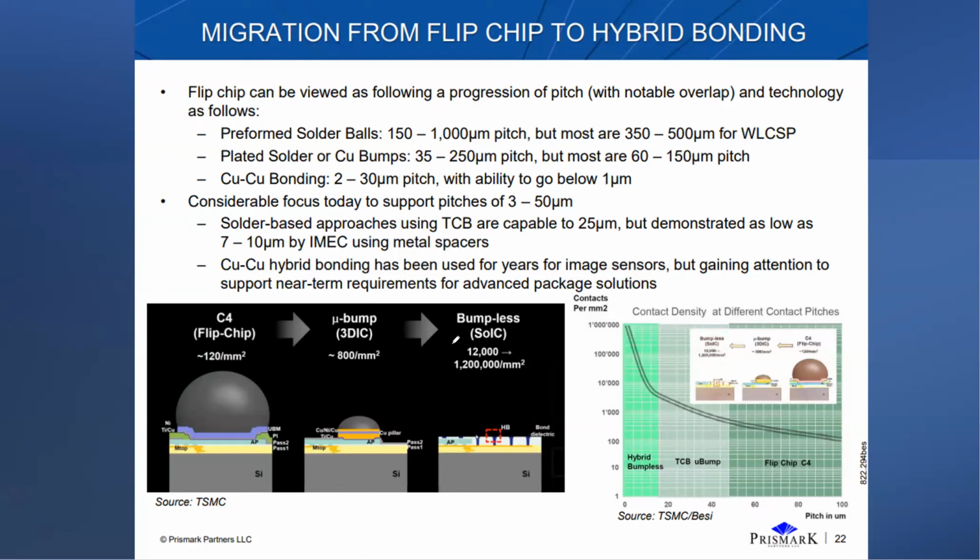And then go to this SoIC, which is the famous interposer with hybrid bonding. This is a hybrid bond. It's bumpless. There's no solder bump here. When you directly connect your interposers with the dies, you use hybrid bonding: copper to copper bonding, and dielectric to dielectric.